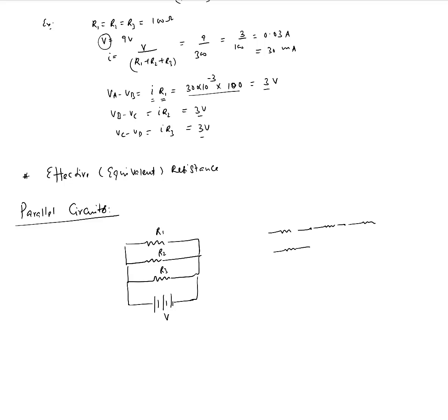Here you have resistors that are tied together at the ends, right? So all these points are connected together. Which means that at all of these points, A, B, C, the voltage is essentially the same, assuming that there is no voltage drop. Let's say this is D, E, F, then the voltage at D, E, and F will be the same because they are basically the same points, right? So this could also be drawn like this.